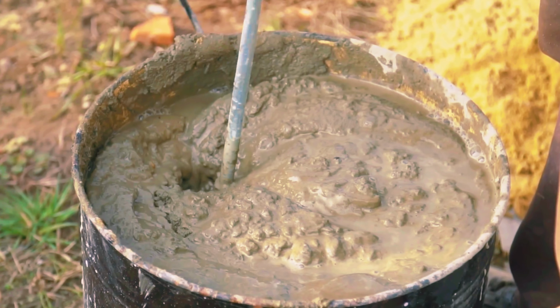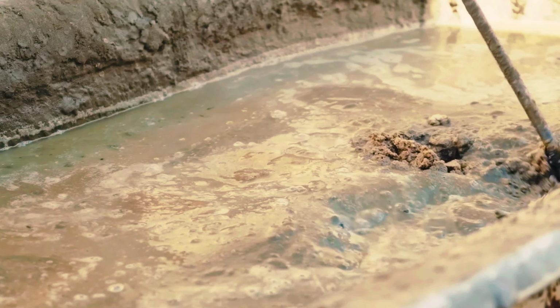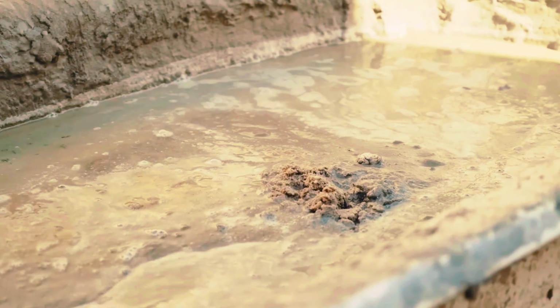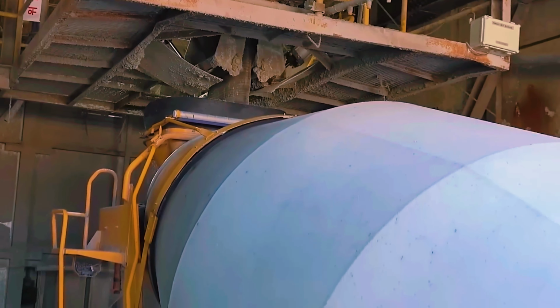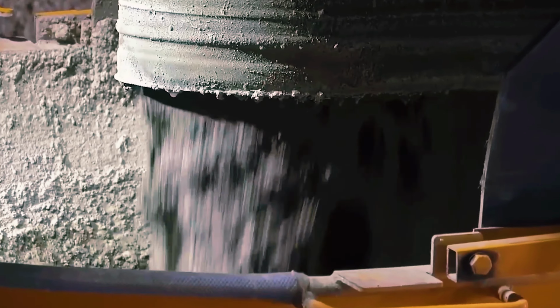When water and cement are mixed together, a paste called cement paste is formed. The hydration process generates heat and continues over an extended period, gradually increasing the strength and durability of the concrete. The mixing process continues until the concrete has a uniform consistency.